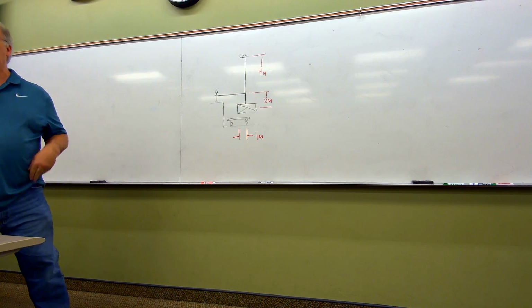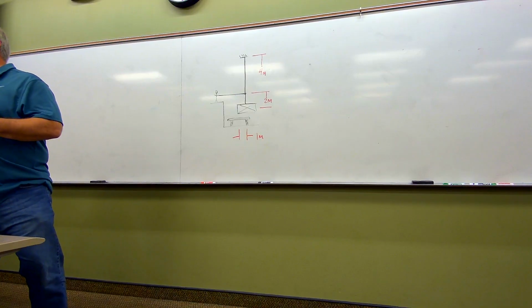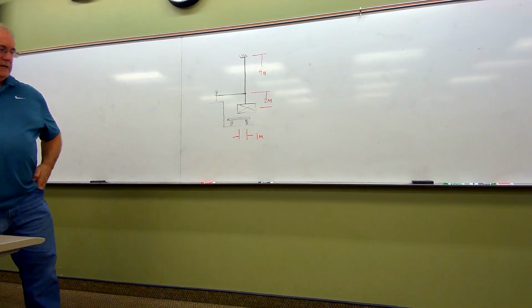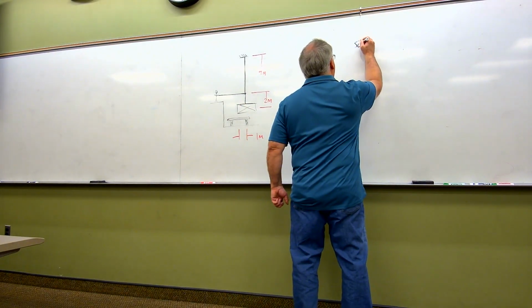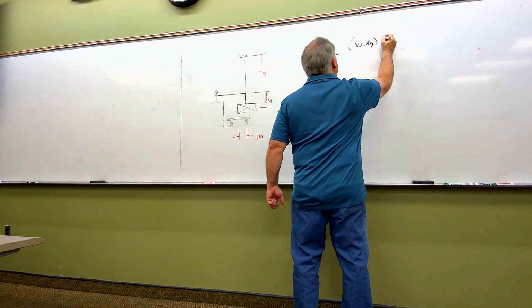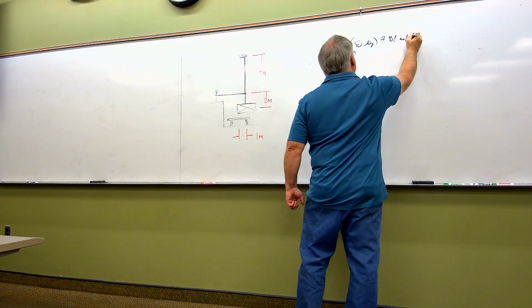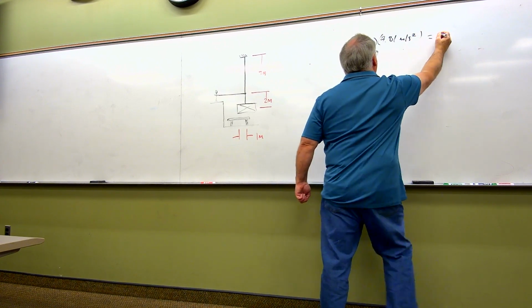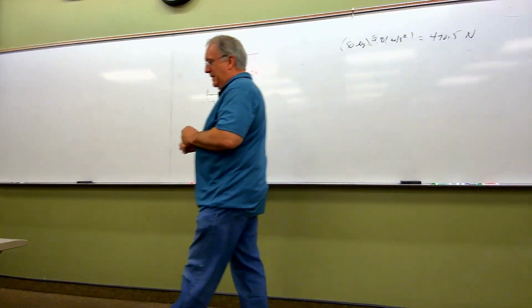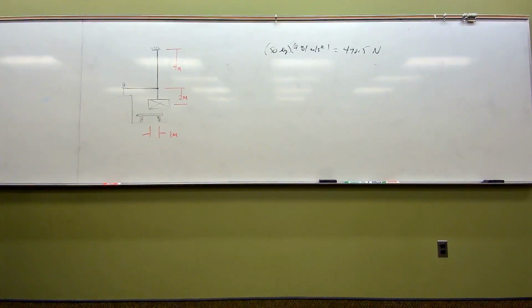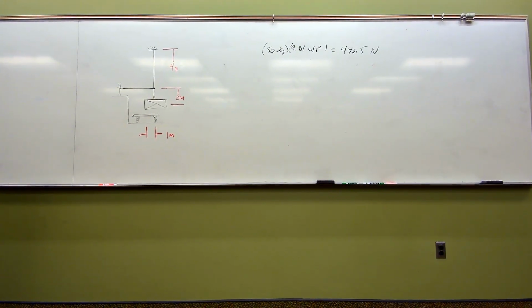So in this case, 50 kilograms times 9.81 meters per second squared is going to be 490.5 newtons. So we know right now, before we even do anything with this, that this crate weighs 490.5 newtons. So we want to figure out what's the force we need to exert on this rope to position this crate directly over the trailer.